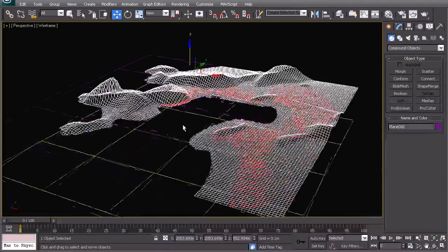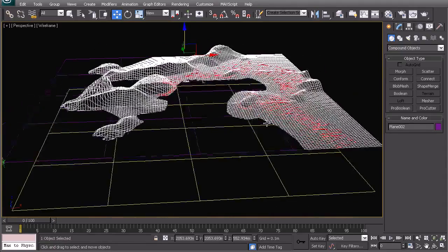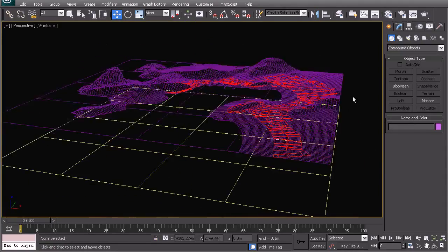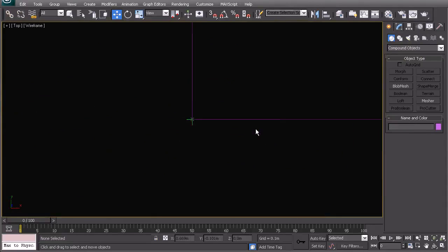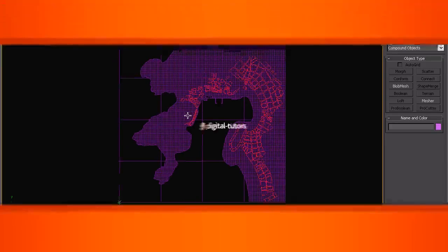In the next video, we will look at how we're going to subdivide each of these two objects into their individual squares, and then we're going to add the texture onto it before we start building the buildings around. So that is it for this video. What we've done is we've brought in the contours that we've moved up into the right altitude. We've created the terrain. We've created the mesh that we've conformed onto it. And then we've gone and cut away using the Boolean tool, the two different objects being the terrain and the ocean. Great, on to the next one.